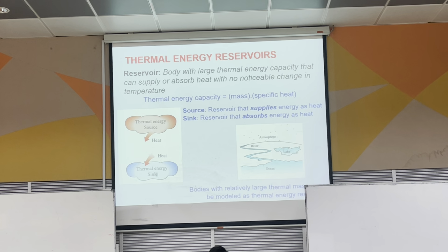But just now we said a cycle always goes back to the initial state, right? But here we just release the air to the surroundings. So where does the initial state come from? Actually, in a way you are rejecting to the surroundings, but then you are still taking in air here. The air that you take in is always the same. So in a way it looks like it is still a full cycle because you are taking in the same air and rejecting the same exhaust. Okay, so this is one example where we call it an open system and open cycle.